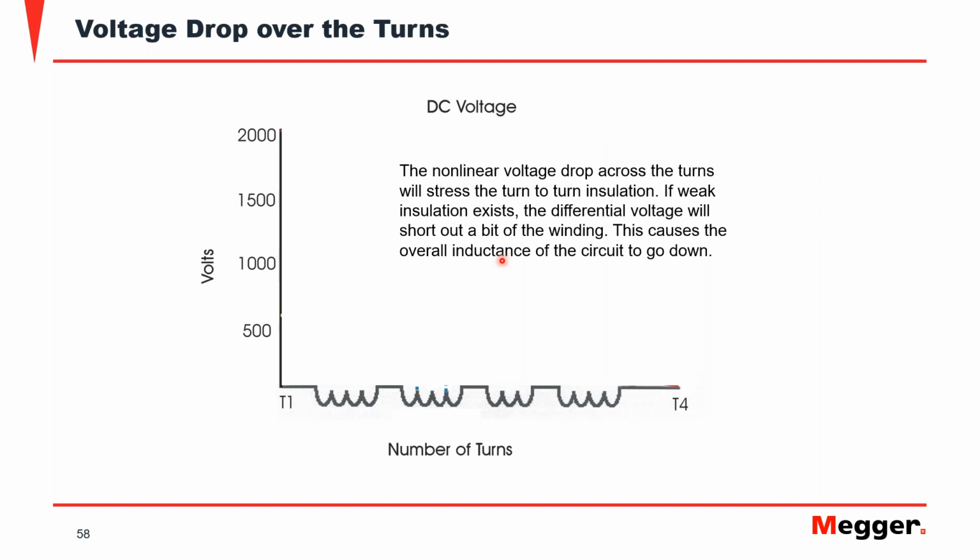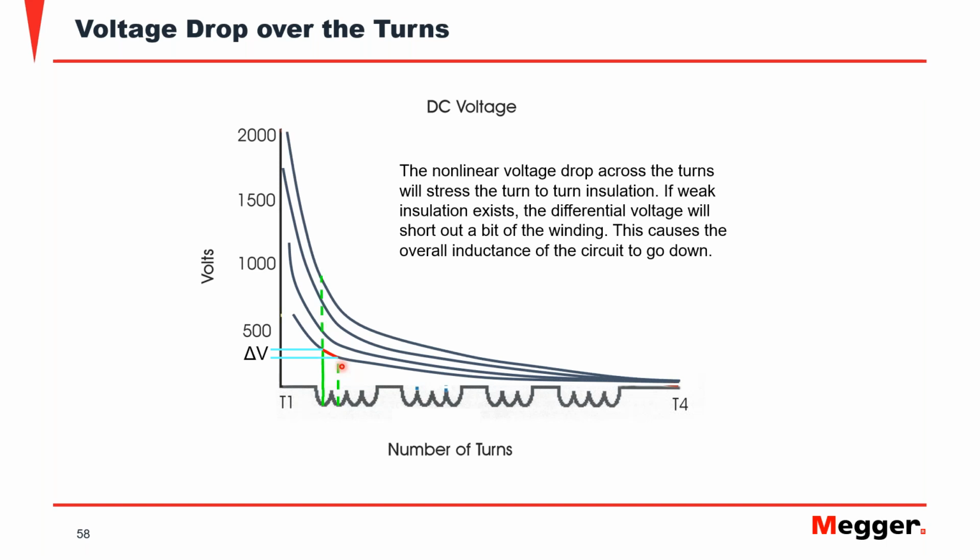So what we're doing essentially is injecting a small voltage, and this small voltage means that I have a turn-to-turn voltage represented here by the red line. And then this will be my delta in the voltage. As I start increasing the voltage, there will be a time where perhaps I will have an increase in the turn-to-turn voltage that's going to be high enough to short those turns.